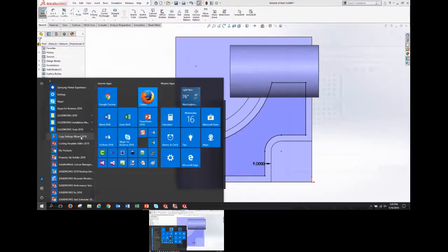It's basically a registry file, I think it's SLDREG actually. I learned recently that if you take out the SLD and just leave it REG and run it, it'll set all the things without having the user interface come up. Just export your settings and then you can carry them over. It's handy when you go from one computer to another, or if you have multiple computers.